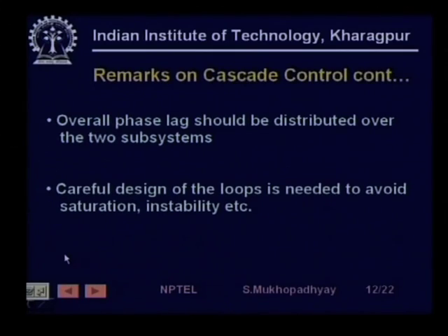Well, there are several other issues which we are not going to consider here. For example, there may be issues of saturation of actuators, and there will be issues of frequency detuning of the inner loop and the outer loop, that is, when the overall gain will peak at some frequency in the closed loop in the inner loop and some other frequency in the outer loop. Such issues are more complicated issues of design, and we need not look at them at this stage.